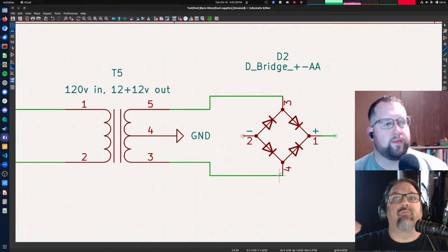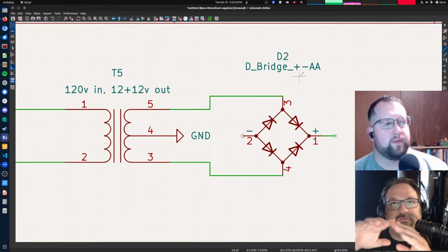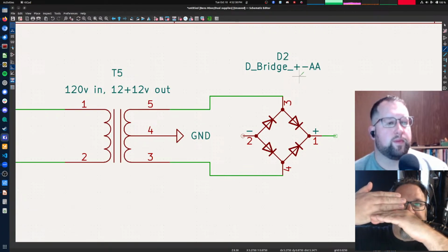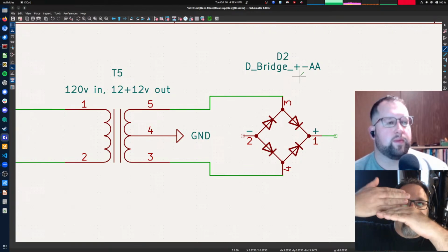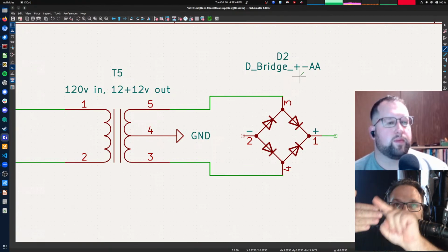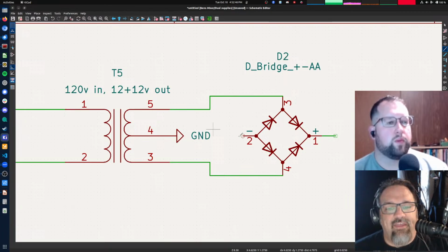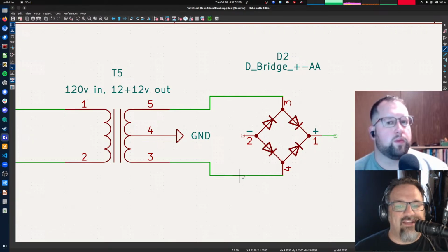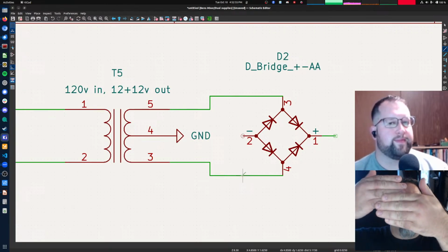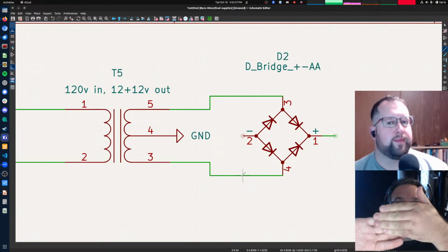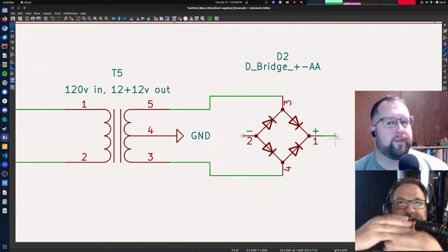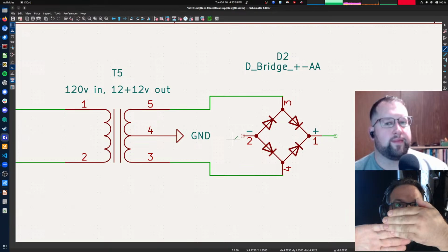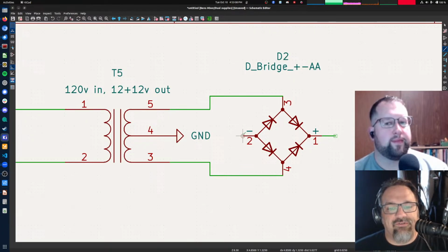What's called rectification is when you've got your sine wave, and you basically take the bottom half and rotate it up into the top half, so now it's got these multiple hills. And then we're doing the same thing on the negative side, where I've got one AC signal up here and one AC signal down here. On the other one, we're taking all of the negatives and folding them down. So out one side I've got all the positive halves of these signals, and on the negative side I've got all the negative halves. But the signals are still very bumpy.